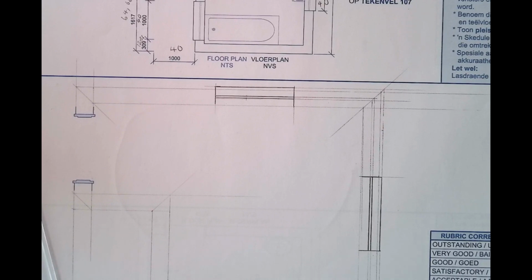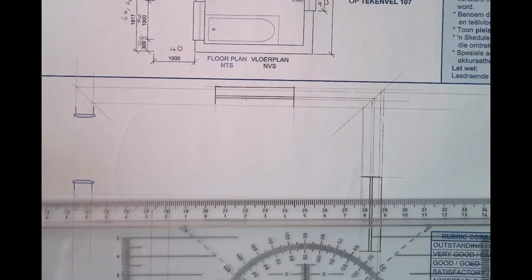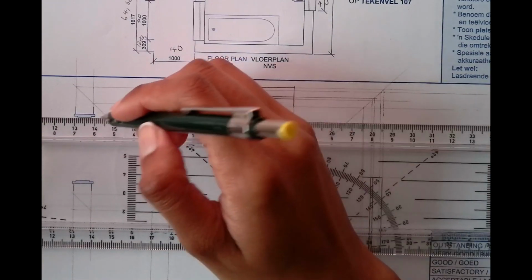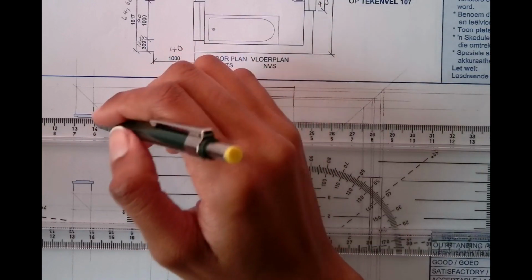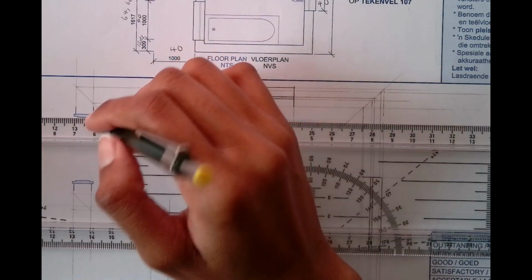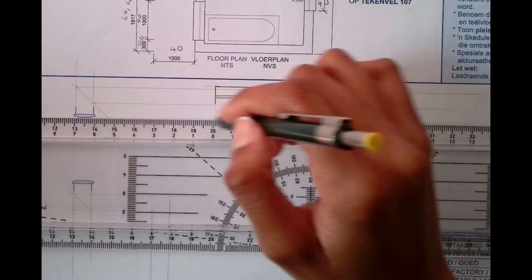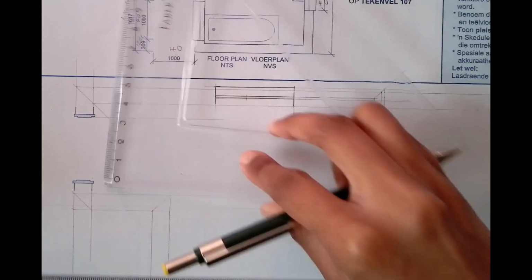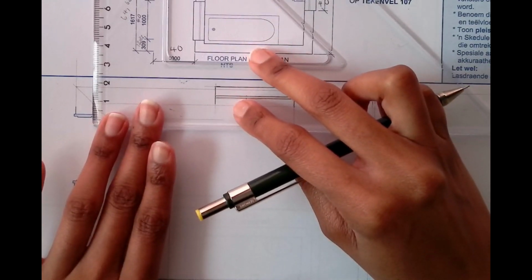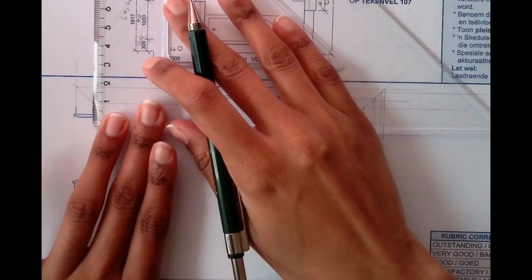Now for the door, we're still going to use those measurements we used previously, where our door thickness will be, you can see that on the floor plan we are given where the door is. So our door thickness will be 40. So getting that to scale 1:25, it's 1.6. So we're just going to come here and put it there.